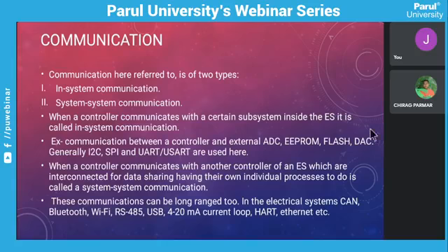It uses I2C. It is used because PWM sometimes is not enough to get the required resolution in the analog voltage. So for that precision, a DAC is used externally. It is available in many ranges from 12 bit to 16 bit, and it uses I2C communication.